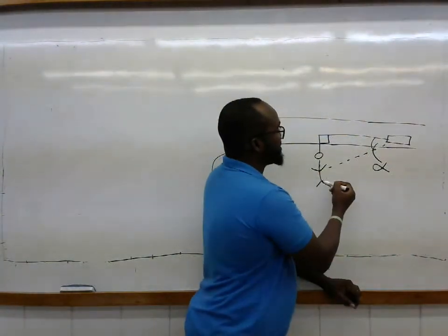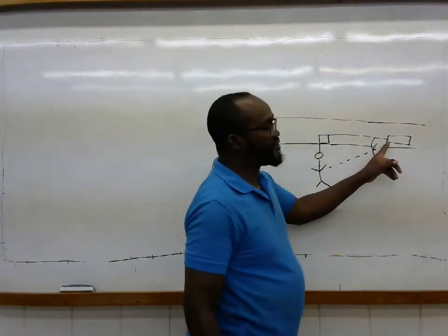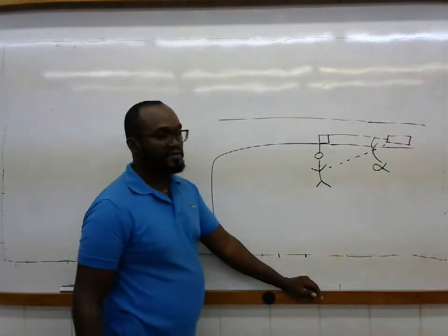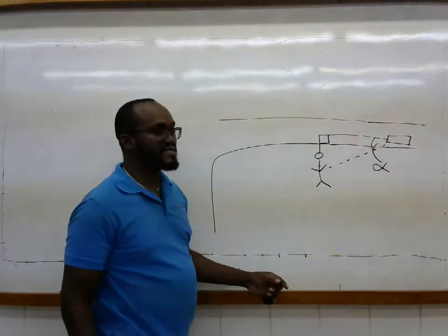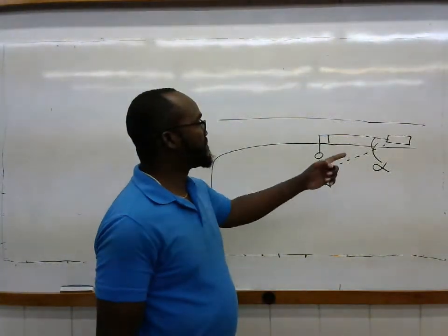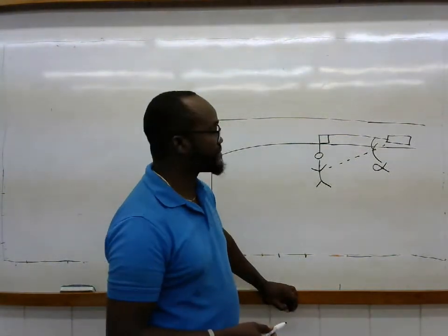Because of that distance, it creates an angle of incidence at which the radar waves hit the vehicle and return to you, the observer. So that angle, alpha in this case, must be corrected for to ensure that the speeds you actually record are actually what the speed of the respective vehicle is moving at.